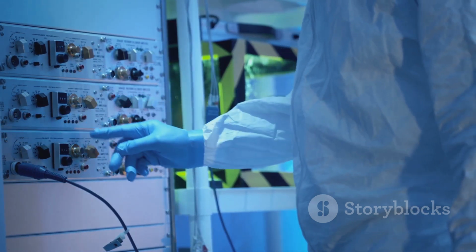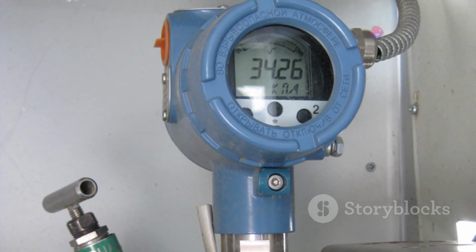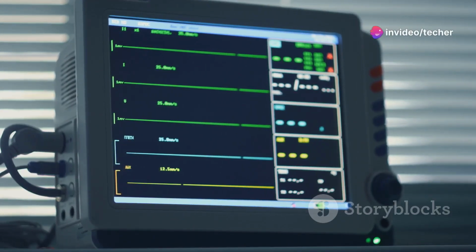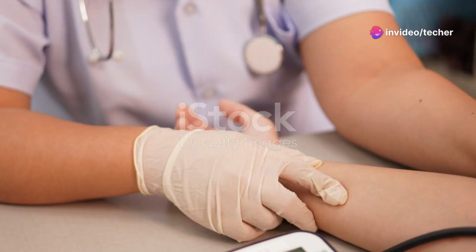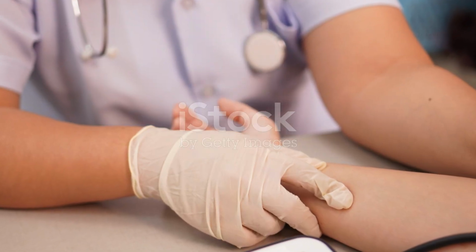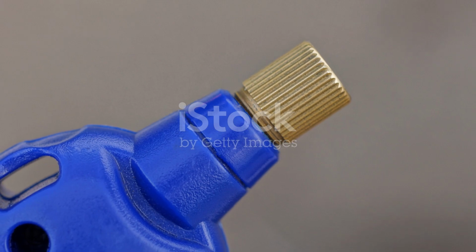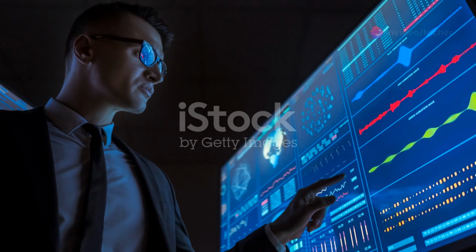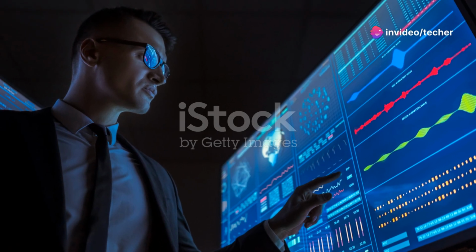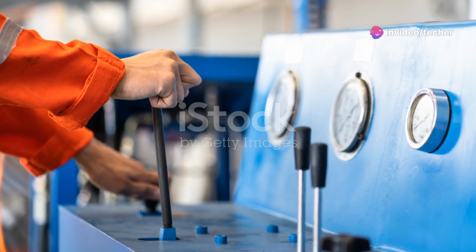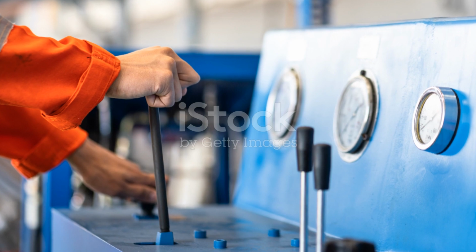Digital pressure sensors, on the other hand, communicate using digital signals, often in the form of high or low voltage levels. These signals are typically connected to the Arduino's digital input pins, where they can be read as high or low logical states. Understanding the sensor's output voltage levels and communication protocol is crucial for interpreting the digital signals and triggering events based on pressure thresholds.